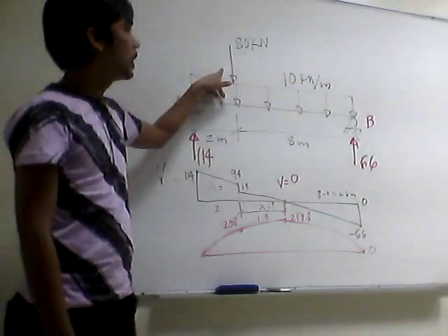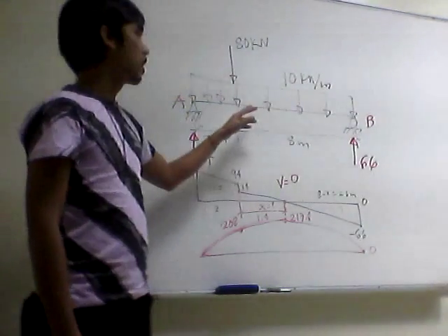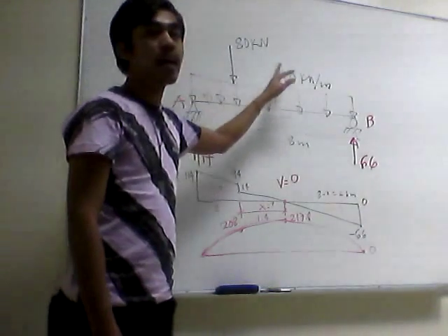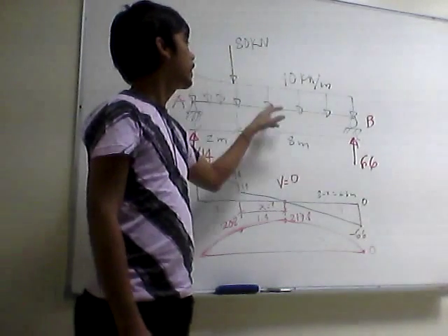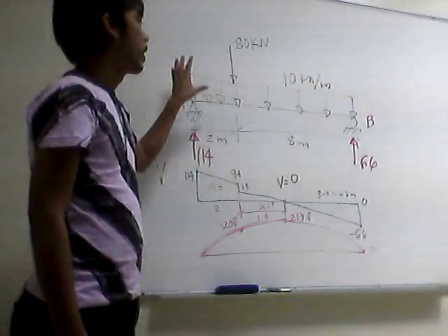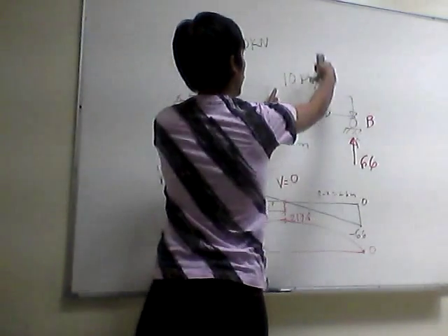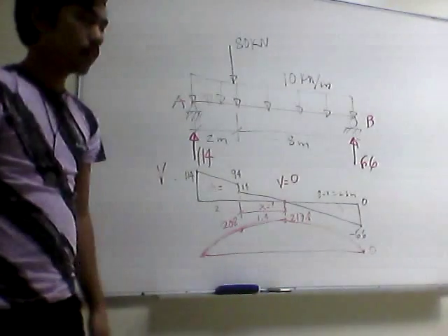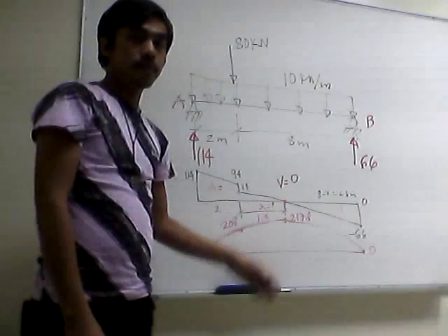Okay? So there are many modifications of this type of problem. You can add concentrated loads here, or you can add distributed loads over the entire span. You can have uniformly distributed loads here and one distributed. The concept is always the same. So that's all for now.